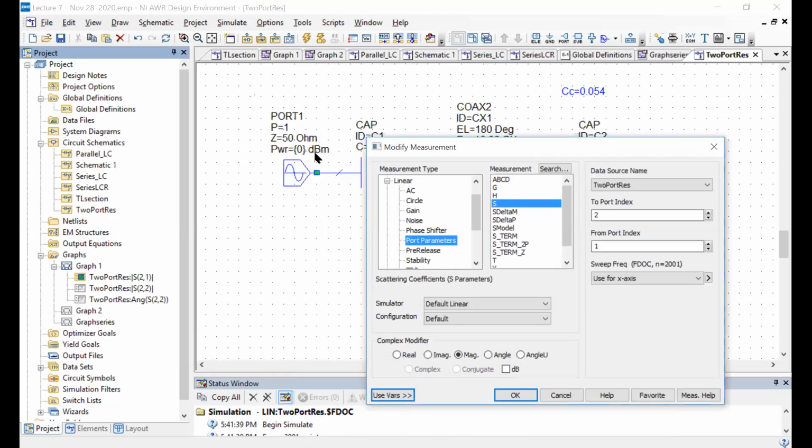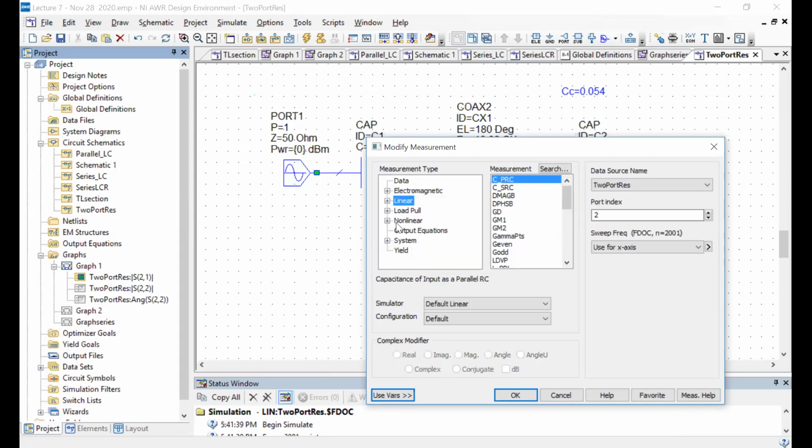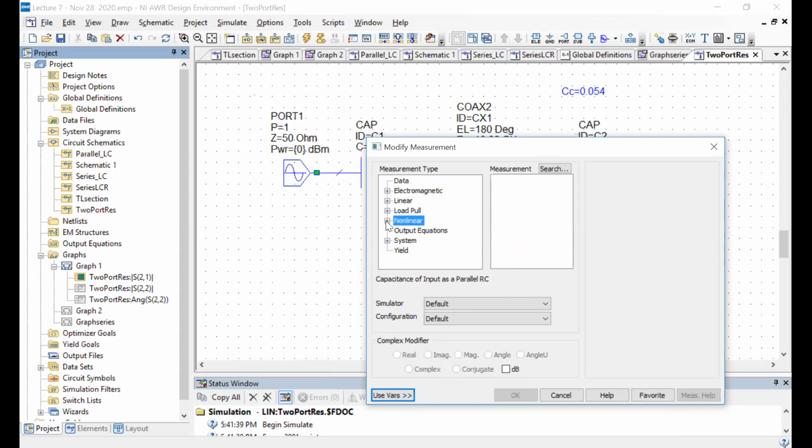It has no meaning. I had explained this earlier also, that if you have a harmonic oscillator which is being forced by some forcing term, the entire response is just scaled by the coefficient of that forcing term. The physics doesn't change. If f is doubled, then everything just gets doubled or quadrupled, depending on what you're looking at. So when you calculate scattering parameters, which are ratios, those powers become irrelevant. Everything gets cancelled out. But here, in the measurement, there's actually a whole bunch under nonlinear.